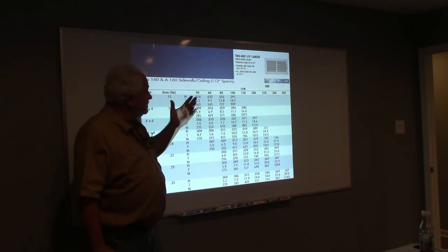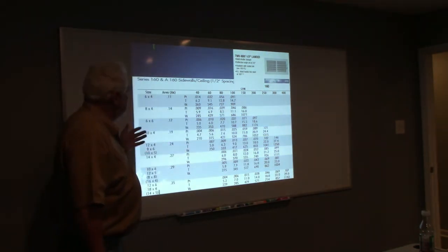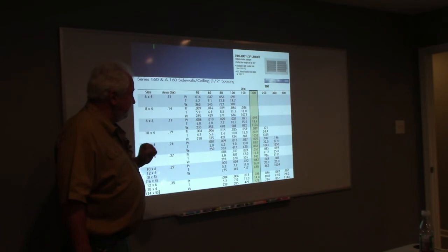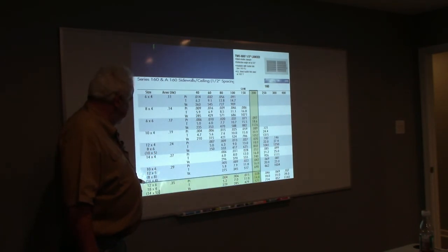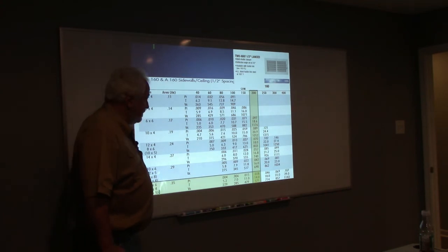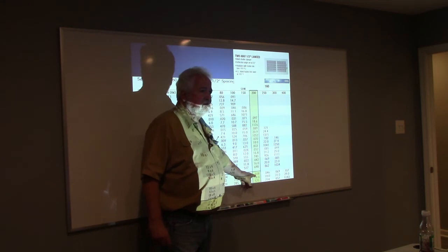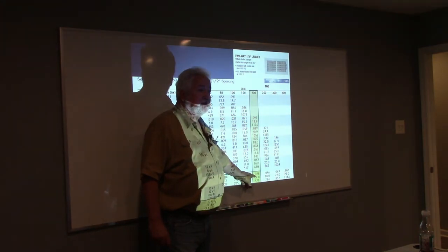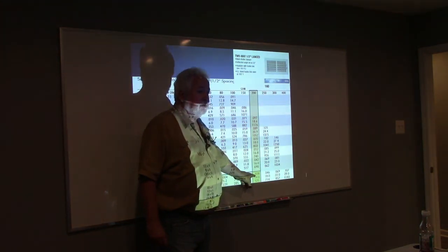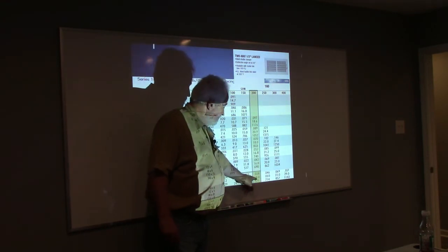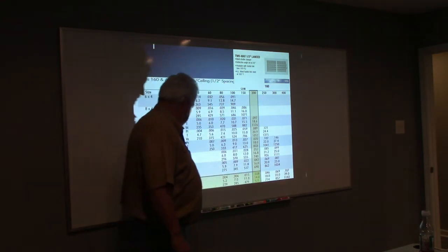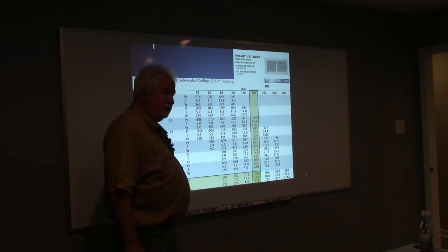Let's try that other grill. That other grill we saw said, well, maybe this will work better. We know we needed to move 200 CFM. We know that we're going to try somewhere around that 12 by 6. Let's try that one, 12 by 6. How about 0.028? We wanted 0.02 to 0.03, is that right? How are we doing? Good. 14 feet, the throw? Good.